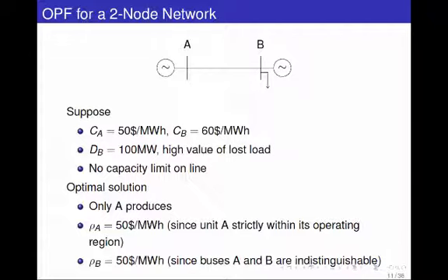And we said that if the rho threshold, so how much is generator B producing? 0. So when would that happen? If you remember what the rho B needs to be for that to happen. It's at least as much as the fuel cost. Exactly. So rho B is at least 60. That much we know already. Okay.